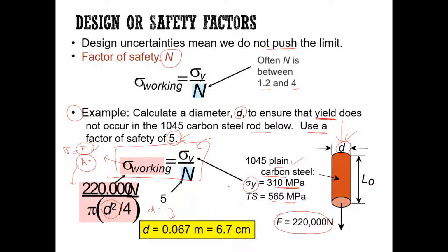Based on this formulation, it gives you an idea how you are going to design your cable, what diameter it needs before it fractures, by considering the factor of safety, which is your N value. Alright, next session we will discuss the failure of materials. Alright, with this, thank you.